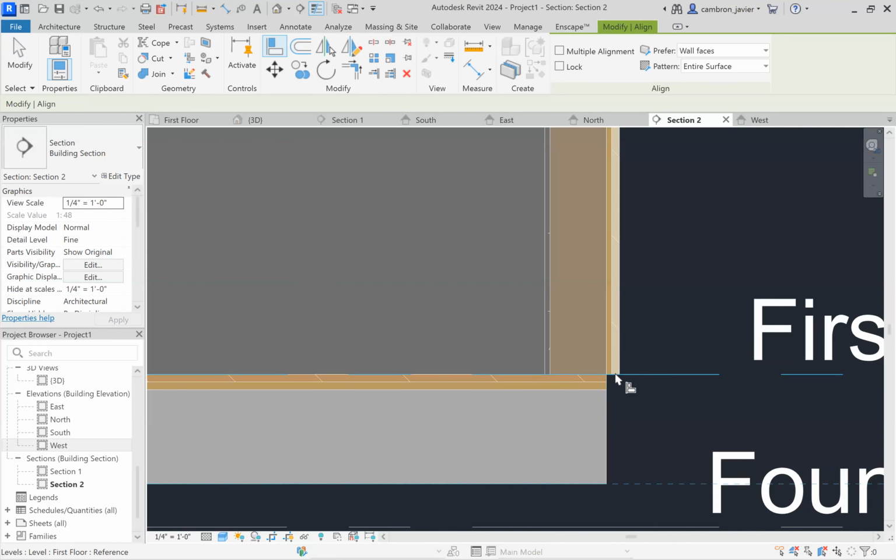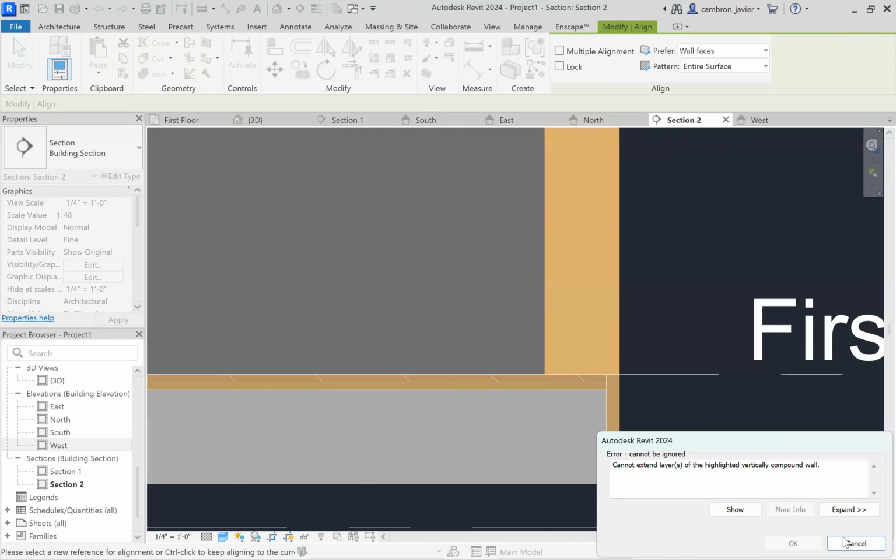And okay, so if you ever run into the problem, and we'll probably have to do this again, where when you hover over, because you have multiple objects, in this case, we have this line on top of the other wall, we could always hit the tab key on the keyboard, T-A-B, and that's going to toggle between all the things that you can select. Okay, so finally I'm going to get to that line, so I'll click there. What happened? A line there, hit the tab key there. Yep, we get the same error.